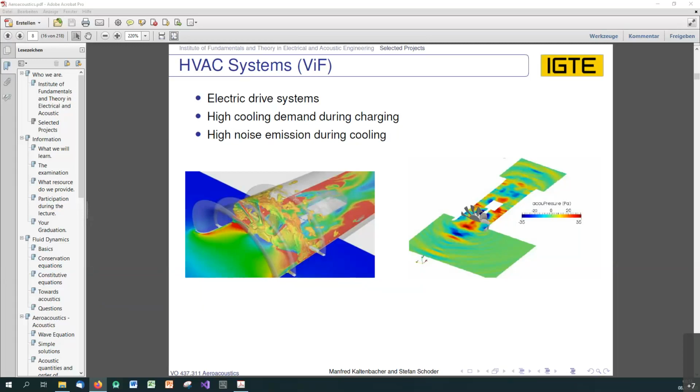And as you see here, this is a chart of the flow speed and some illustration of the vorticity structures that the fan is producing. During the rotation of the fan, it produces vortical structures, and these vortical structures then result in accelerations of the fluid, or are consequences of the accelerations in the fluid. And these accelerations connected to vortical structures are flow-induced sound sources.